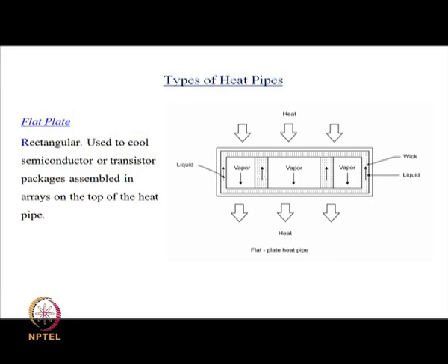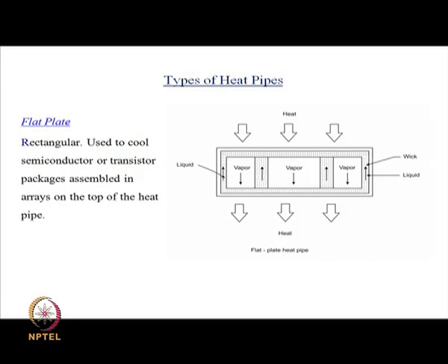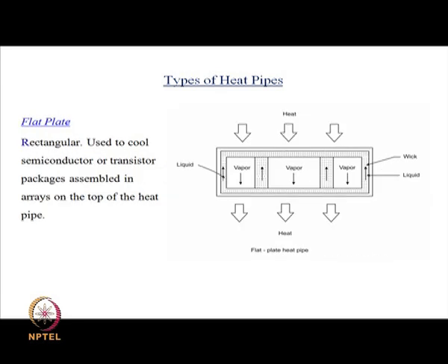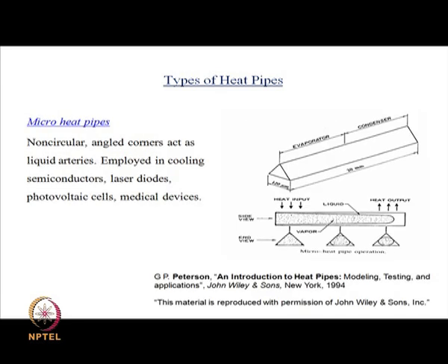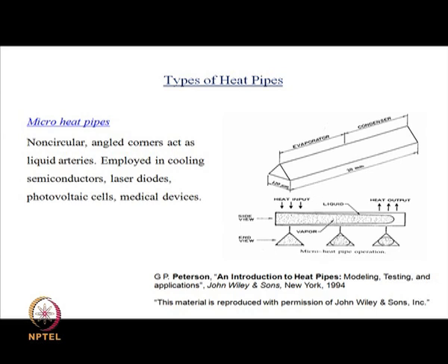So, some of the types of heat pipe that you see, I am still in the wicking part of it. So, you have a vapor flow, which you have a heat input, and suppose you have a series of power transistors which are bulky in size, where you can still use wicks, you can keep them at the top, and the heat is going to be let out from the bottom. So, vapor will flow from the top to the bottom, and through the wicking action, liquid will move in the reverse direction. So, against gravity, it will go up, come in contact with the hot spot, evaporate, and the vapor will come down and condense at the other spot. So, these would be possible for slightly larger applications.